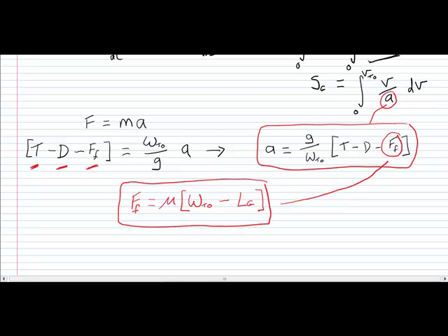I've also given you in the lecture notes some typical values for different types of surfaces for this parameter here, the coefficient of friction. I think I suggested for the aircraft that you're designing to take off from a dirt strip in the Australian outback that a value of mu of 0.04 would be a sensible number to pop in here.